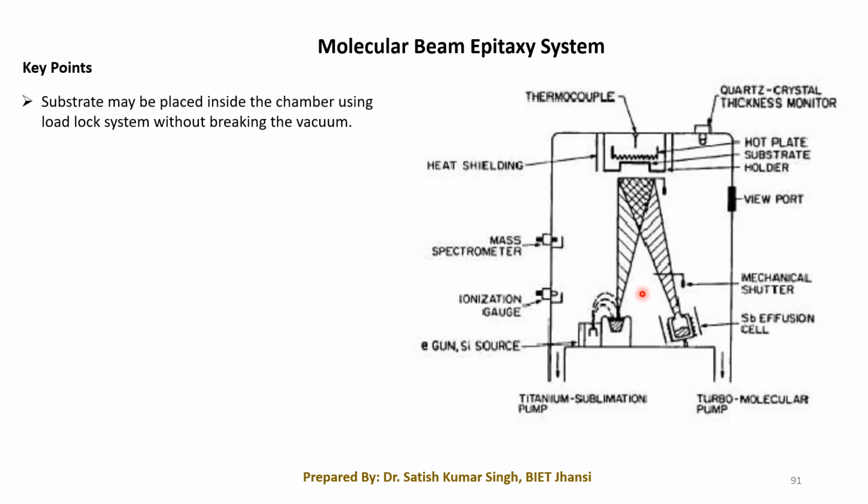But in the case of molecular beam epitaxy, we generally do not use the rotary pump or diffusion pump because those pumps use certain oils, which have disadvantages such as back diffusion. We do not prefer that.